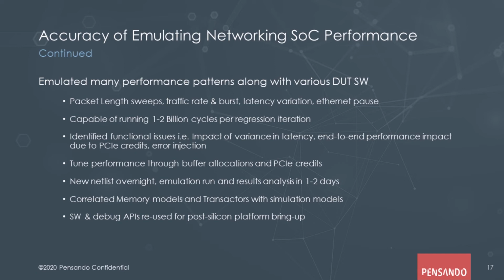Initially we all had a doubt: how accurate is this model? How is it different from simulation? The transactor may not be as accurate as we are thinking. So we also undertook correlating the ZeBu transactors with our simulation transactors. And post-silicon also, we saw the same results as we were seeing on ZeBu, with very sub-percentage level accuracy. So it's very, very highly accurate, and we see a lot less variance post-silicon.